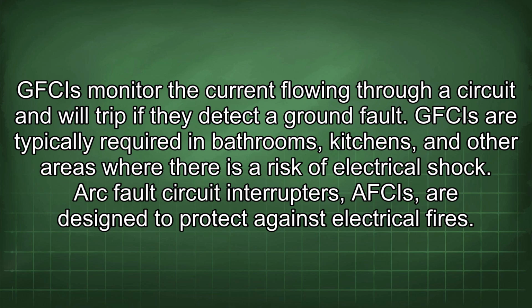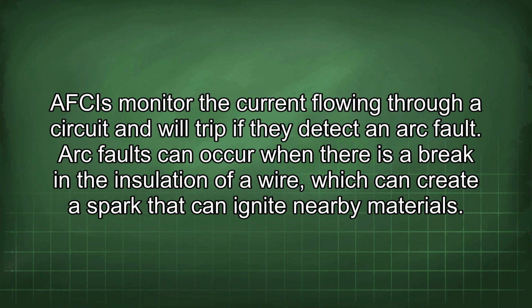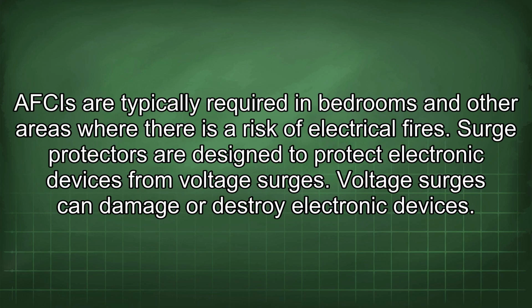Arc fault circuit interrupters (AFCIs) are designed to protect against electrical fires. AFCIs monitor the current flowing through a circuit and will trip if they detect an arc fault. Arc faults can occur when there is a break in the insulation of a wire, which can create a spark that can ignite nearby materials. AFCIs are typically required in bedrooms and other areas where there is a risk of electrical fires.